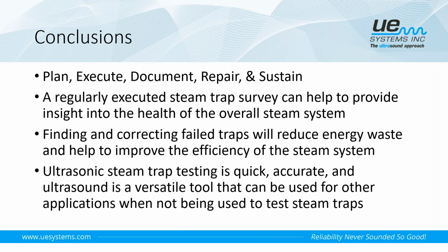And then really everything that I've talked about so far will help you to sustain doing that over and over. So again, depending on the size of your facility, how many steam traps you have, what the steam trap is being used for, typically we'll see people doing at a minimum annual steam trap surveys, but then sometimes it's going to be biannual or twice a year.